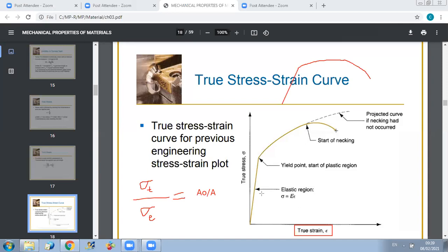You can just represent the true stress and engineering stress as a function of L. If you do it as a function of L, which is the length of the specimen, you can compare both because you will have the same coordinates along this axis for both. Because in general, when you plot the engineering or true curves, they have different axes. The true strain will be smaller than the engineering strain in case of tensile tests. This is due to the definition, of course. So we will see examples together after how we can draw the two on the same graph and how we can compare.